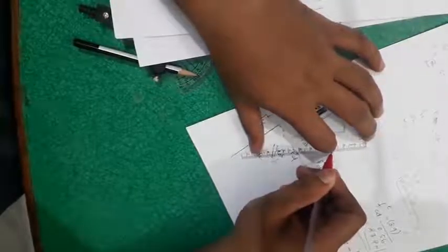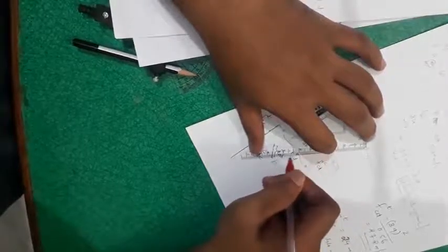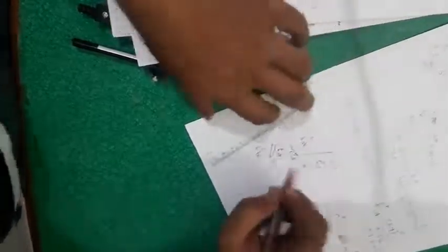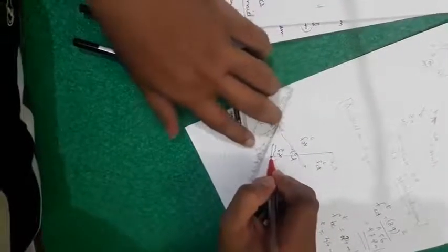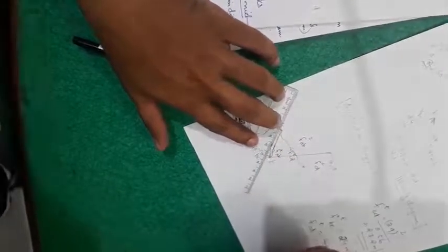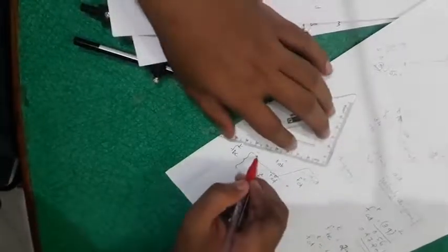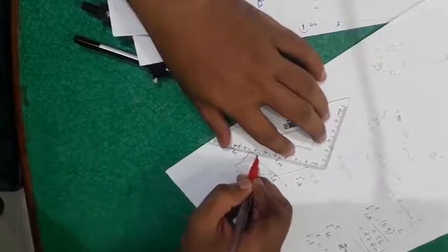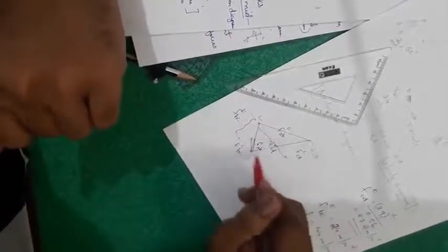Join from the point A first to B, right, A to B, and from here to C and C to D. So the red line represents the links in the acceleration diagram, and now we have to mark the center of mass of each link, the point where the center of mass of each link is acting. It is given in the question.